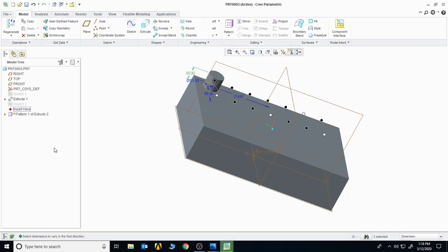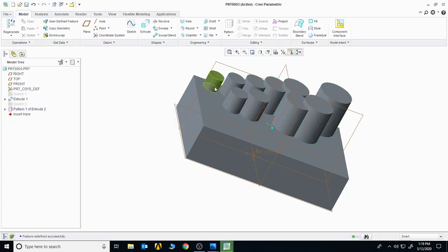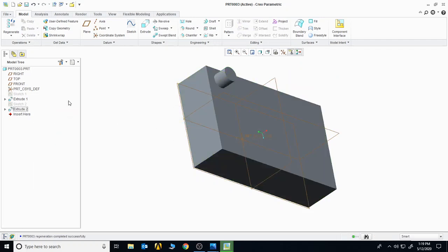If you want to change the diameter, you can also do that. Right click here, press the control button, click on the diameter, edit the diameter. Let's suppose we want an increment of 10, enter the value 10 here and click on OK. So you can see the changing diameters in incremental order. For decremental, you have to add minus with the entered value. If you want to delete it, so get it deleted. So that was how the first type of pattern works, that is dimension pattern.